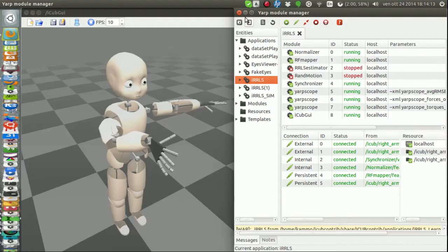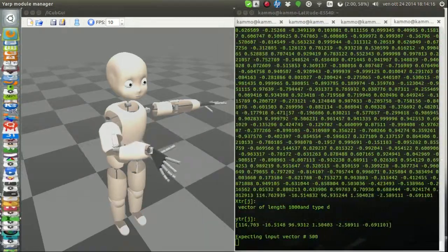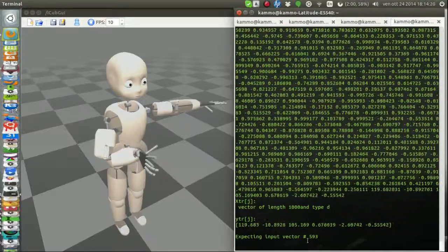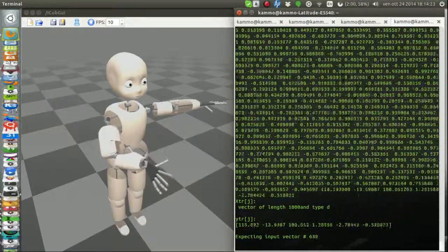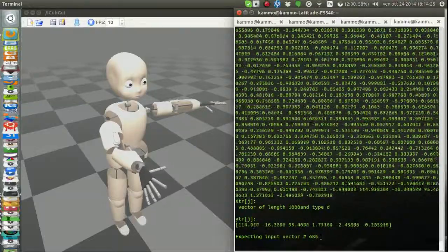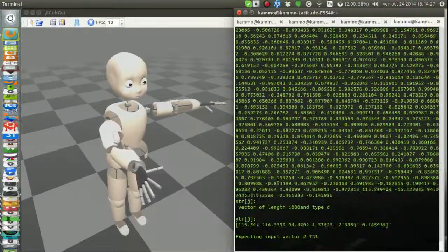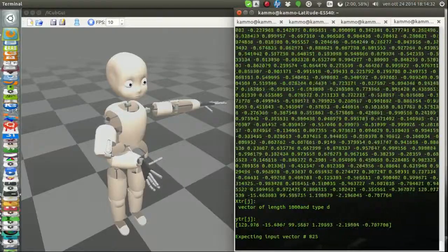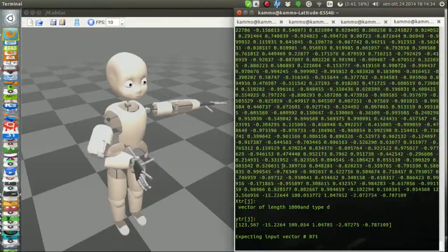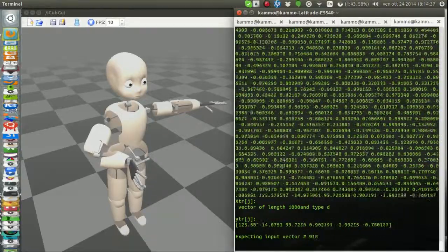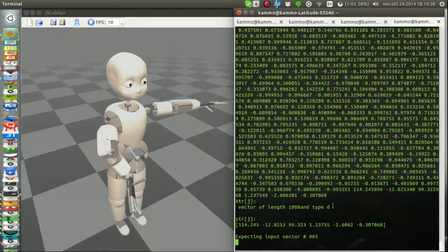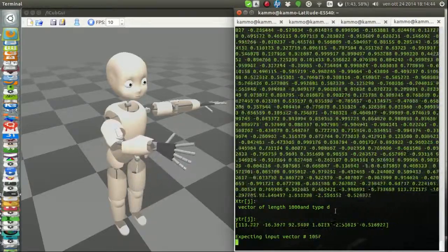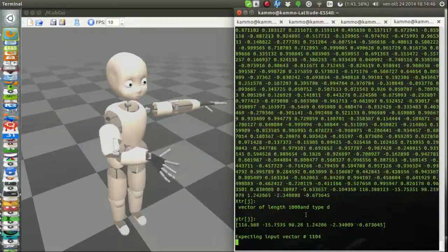So now let's move to the terminal. At the moment, the iRRLS estimator is receiving the mapped data, and it's waiting for 5,000 samples, which correspond approximately to 4 or 5 minutes of operation of the robot. It's waiting for 5,000 samples for pre-training and model selection.